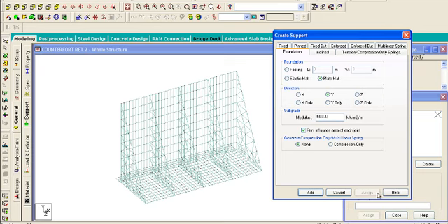You can set the spring to compression only, but we are going to leave it for some reasons. By the time we do our combinations, there shouldn't be any issue. If you set it as compression, it means the springs cannot take any tension, and we are going to have a little challenge when we are applying the horizontal loads.